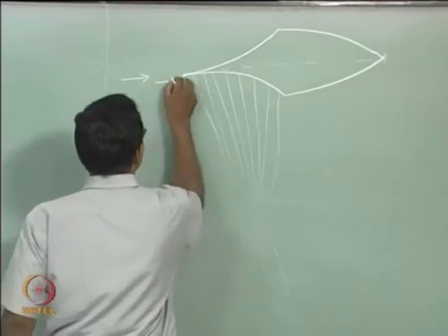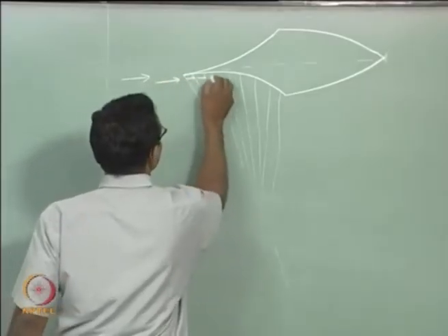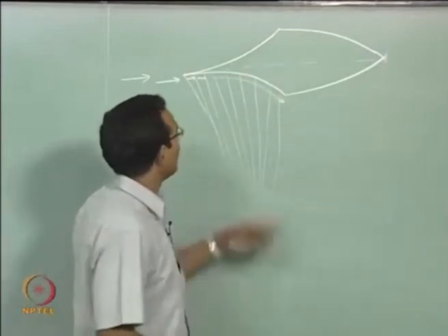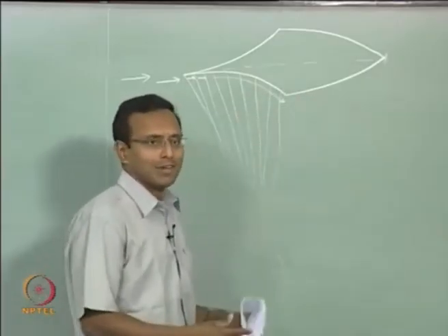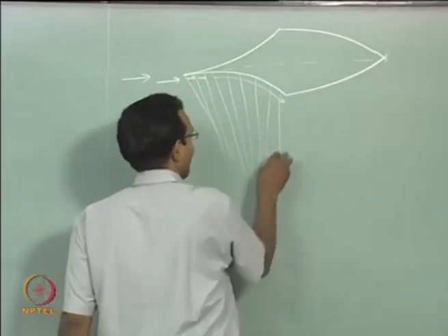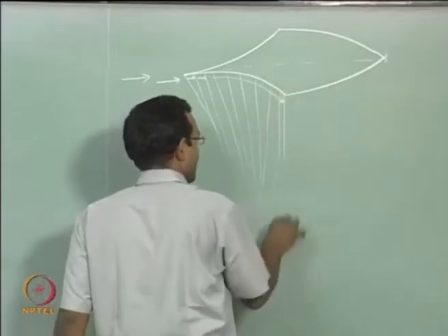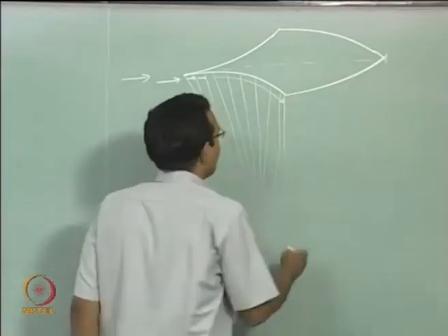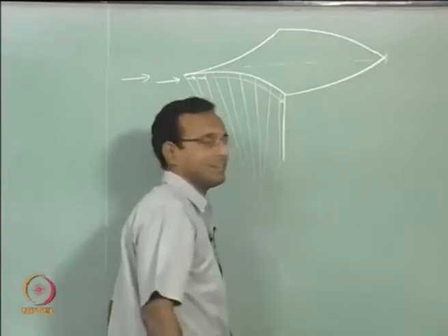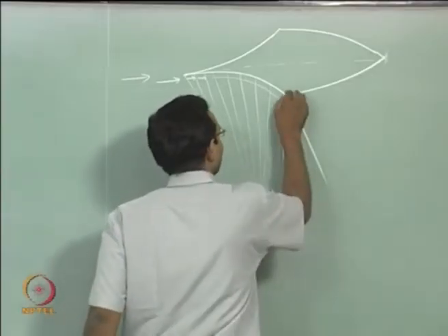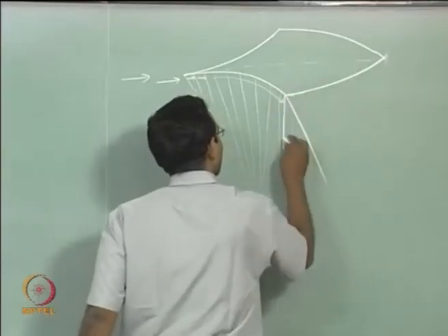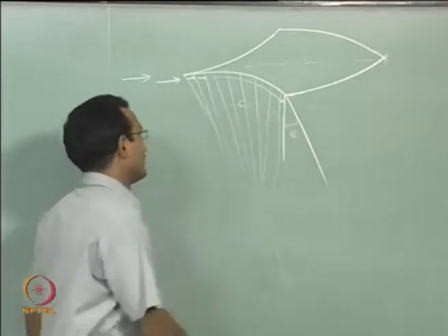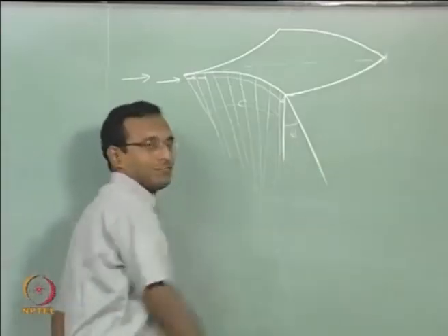So what is going to happen is the flow is coming here and it is slowly turning along the wall all the way, and it is going to come to this point, and it is coming out at some high angle this way. Immediately I am telling it is going to 0 angle there. What is that? That is an expansion fan. Okay. And we know that the last compression wave there is also a Mach wave, which means my expansion starts immediately there, and this whole region will be my expansion fan. This whole section is my compression fan. This is my expansion fan.